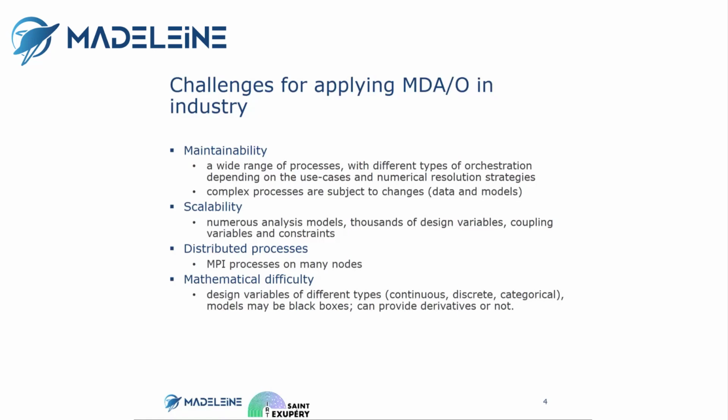And then scalability is also key, because we have to deal with numerous analysis models, thousands of design variables, coupling variables, constraints, and so on. We have also to think about distributed processes, and at IRT we have specifically worked on MPI processes distributed on many nodes. And obviously there is some mathematical difficulty within MDO, for instance, handling different types of design variables, but also handling black boxes and software that can provide derivatives or not.